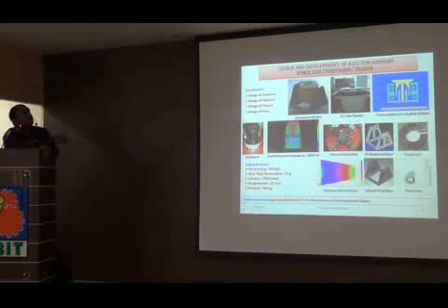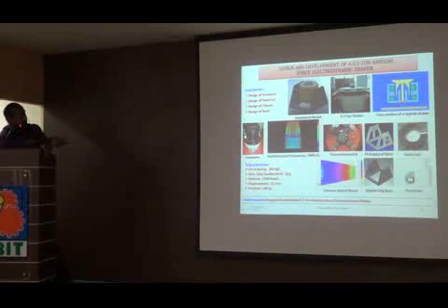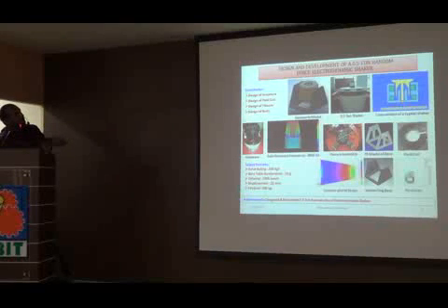So what are the critical components in a shaker? We call them the armature, field coil, fixture, and body. Armature means the conductor which carries current, and it is required to be designed for above 2000 Hz because of its operation range. So we have designed it to have a 3000 Hz frequency, and we realized it and also made the hardware.